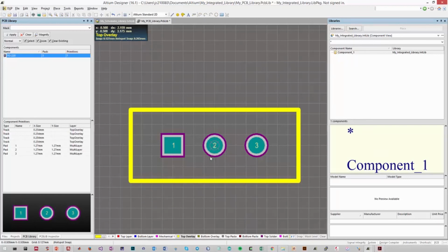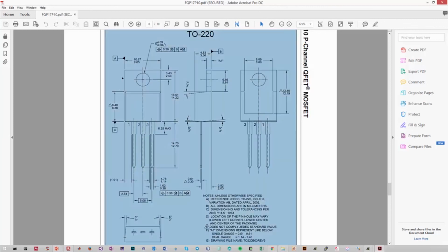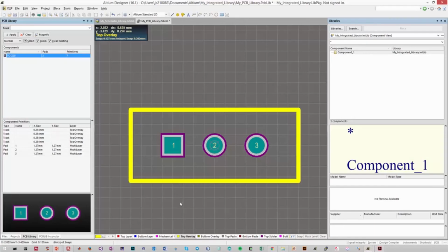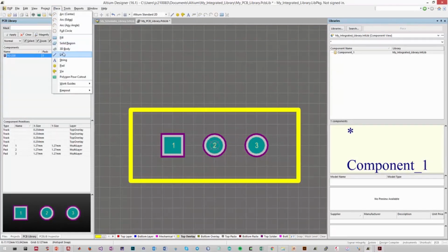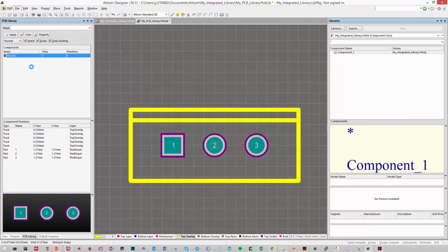There's my transistor outline. One more thing that will be useful is to indicate where the heatsink attachment is on the transistor so that you can get the correct orientation. So remember, pin 1 is on the left when you're facing it, and in that case the heatsink is on the back of the device. So this tells us that if I'm going back to Altium, I need to draw a single line to indicate where the heatsink is, just like so. That will suffice. So that's the correct outline. There's my heatsink back, and the gate and pin 1 is on the left side of the component. So I'll save that, and there we have it.